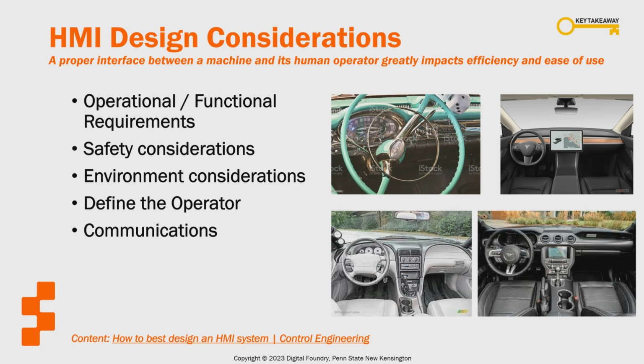The key to a successful HMI system implementation requires a well-grounded definition and understanding of the operator's requirements. For an expert user where more sophisticated controls are desirable, there may be multiple layers or levels for interfacing with equipment. However, once you've established how an HMI will look, feel, and operate, consider how the HMI will connect to and communicate with the core equipment or system under control. Typically, communication can be achieved through several approaches: hardwire connections, serial bus connection, or wireless connections.